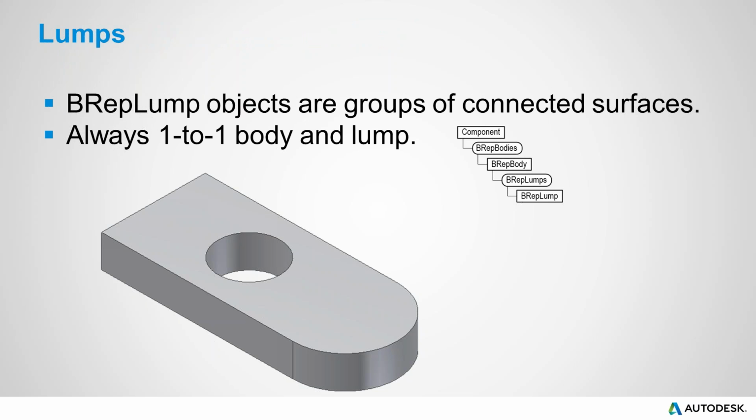This is something that's kind of standard. The BREP idea is very common in the industry. Almost all of the solid modelers you would use have this same concept of a BREP, where the solid is defined by a set of surfaces. The structure that Fusion has is industry standard, and so the API exposes this full structure, but it happens that lumps aren't really used by Fusion.